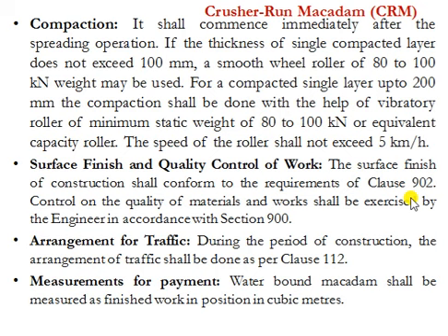When we consider environmental safety, the nearby streams, watercourses and lake reservoirs shall be protected from contamination by soil erosion from the area exposed during excavation, by constructing temporary berms, dikes, sediment basins, etc. By the use of temporary mulches, seedings, or other controlling devices, we can prevent soil from entering the water body through soil erosion.